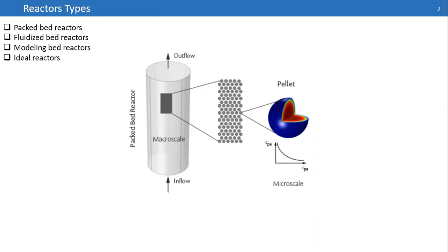So my question is, when is it better to use a CSTR? When is it better to use a PFR? When I say CSTR, you can just assume a tank with a mixer, or a fluidized bed reactor operating under the homogeneous fluidization regime or bubbling fluidization regime.